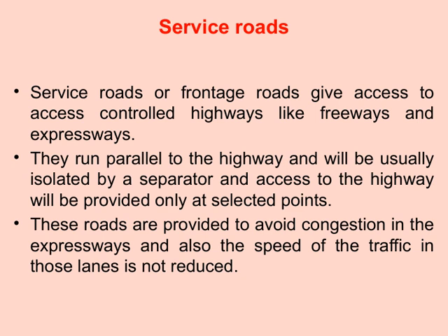The main purpose of these roads is to reduce congestion on the expressway or freeway by allowing local traffic to enter and exit without directly impacting the high-speed lanes. This setup also ensures that the overall speed of traffic on the main highway remains high, as vehicles entering or leaving don't have to weave through slower-moving local traffic. Connecting these points to the broader theme of highway design, service roads are essential for balancing accessibility and maintaining high-speed travel, ensuring that our highways are both efficient and safe for everyone.